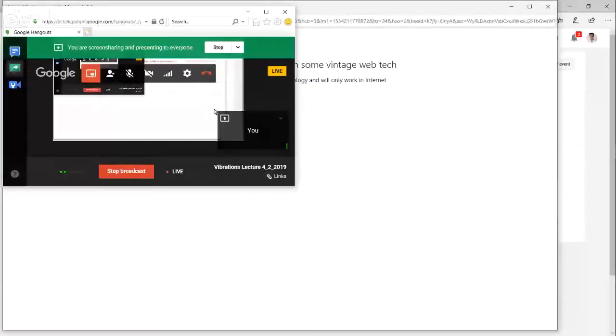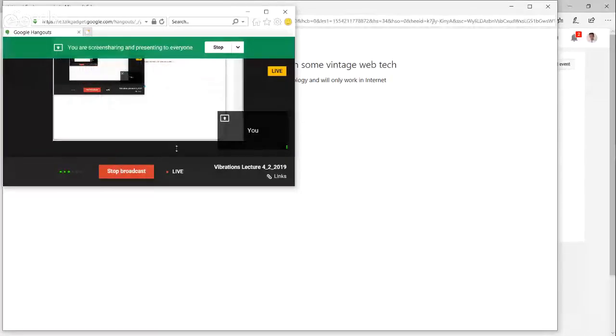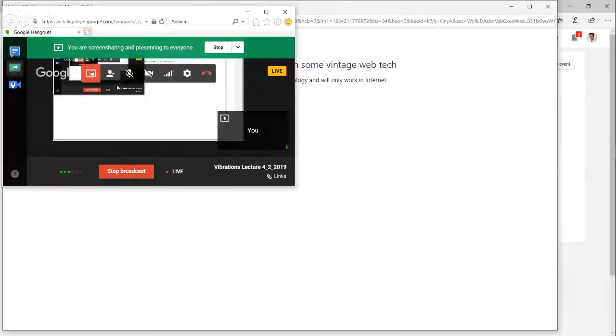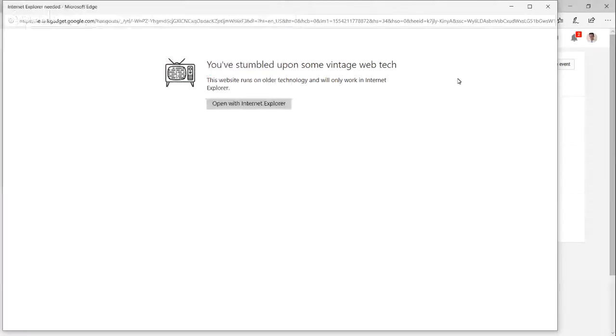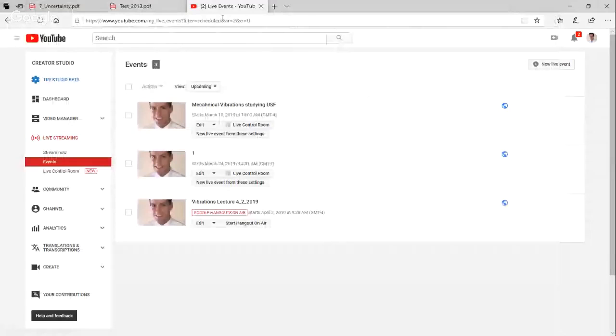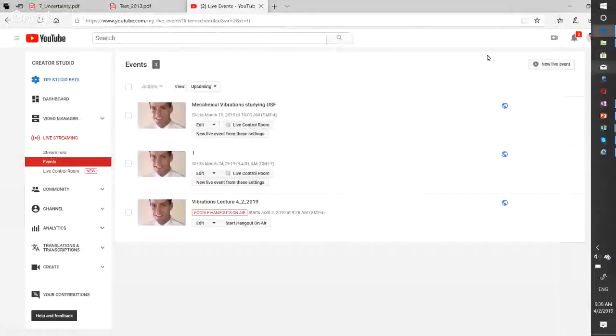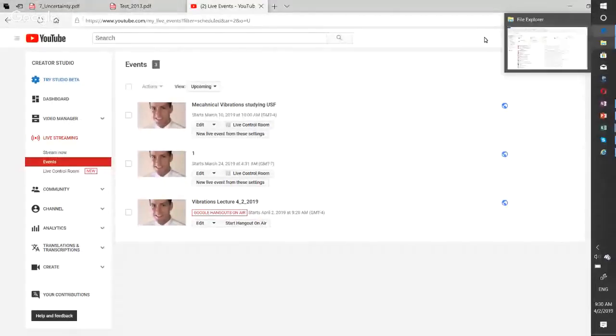Frequency response gives us an output in terms of an input. In other words, if I hit a system or a structure with a certain input, the response that I get from that input, with respect to the input, is my frequency response. That's a simple, layman's way to put it. We went through the mathematics last time, and it was only the bare minimum I could give you to talk about it intelligently. We could spend an entire semester looking at the details.